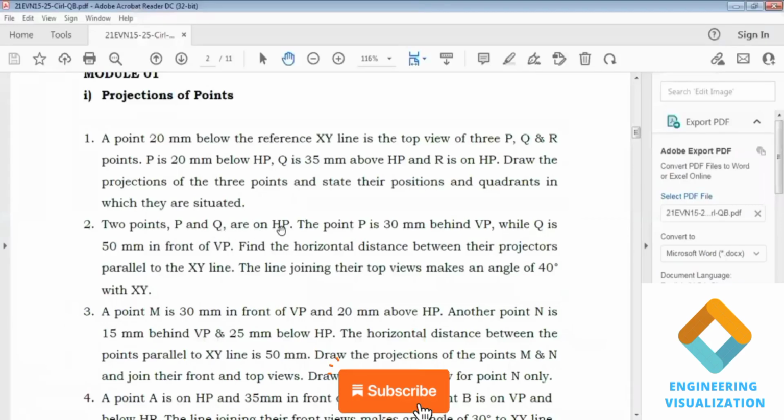Here two points P and Q are on HP, or on HP means front views. The point P is 30 mm behind VP. Behind VP means this top view lies in the second and third quadrant, while Q is 50 mm in front of VP, which means this top view is lying in the first and fourth quadrant.